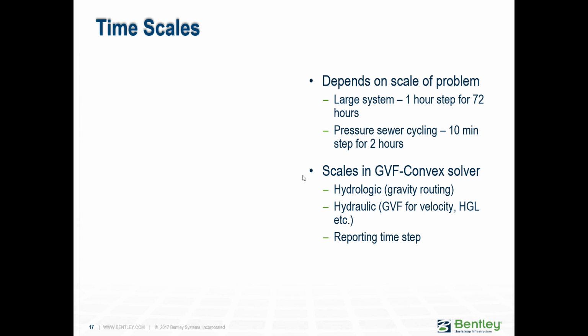I don't know if you remember, guys, but when we did the first demo yesterday, these two, hydrologic and hydraulic time steps, were different. So at some point, our profiles would just disappear. You wouldn't see the hydraulic grade line or the energy grade line. And it's because the hydraulic time step was much bigger than the hydrologic. So when in doubt, always set them to be the same.